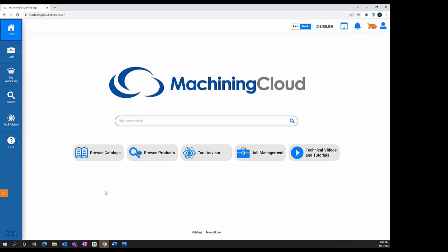So obviously before you start that job, you're going to want to know some information about what the tools are going to do. So you're going to want to know what material it is, hole diameters and depths, internal, external radii, and obviously if you have a blueprint, drawing or model that you can use before selecting the tools, even better. But obviously I know what Jeff wants, so I will start today by showing you the tools and how I'm going to set them up, and then pass them over to Jeff to use in Vericut.